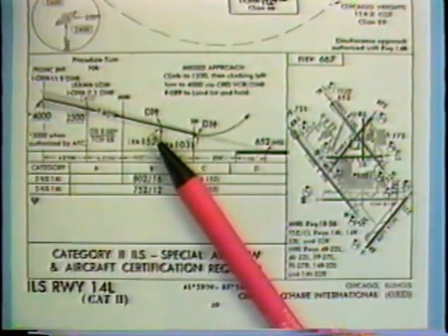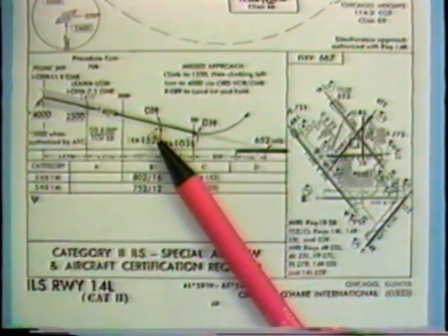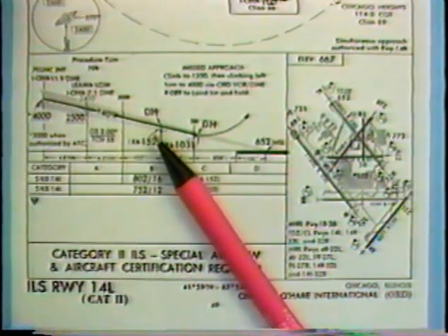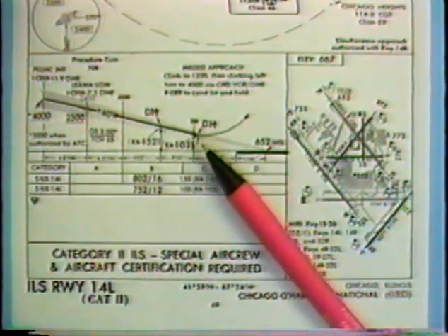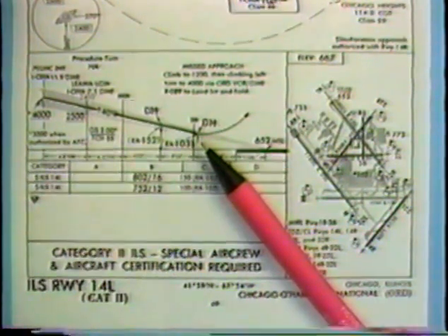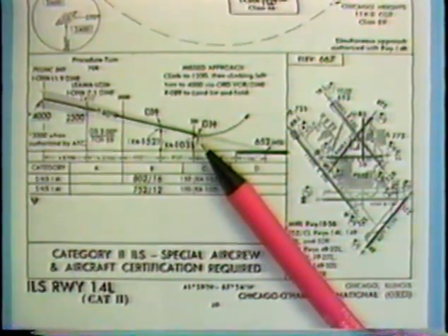The missed approach point on a precision approach occurs when the airplane on the glide slope reaches the decision height. At this altitude, the pilot must either make visual contact with the runway or runway environment or execute a missed approach. There is no leveling off at decision height. Either continue visually to a landing or immediately start the missed approach.